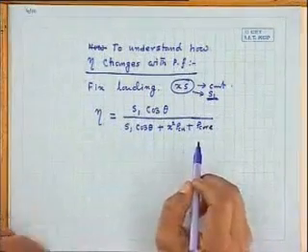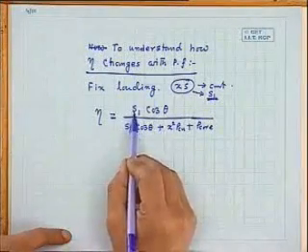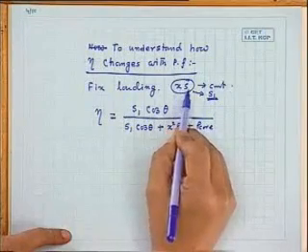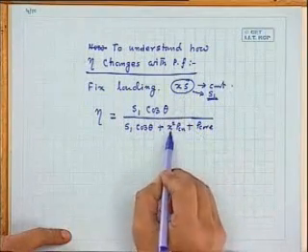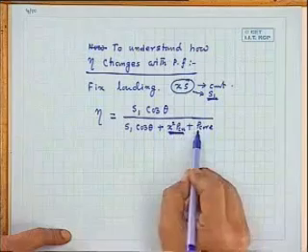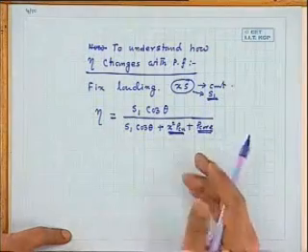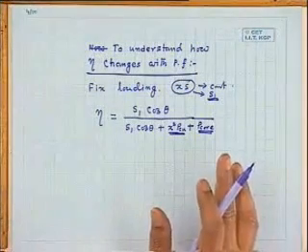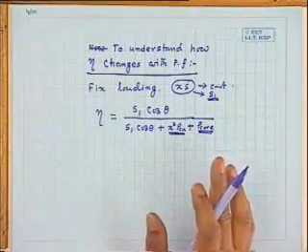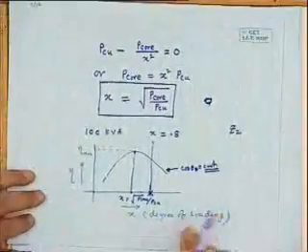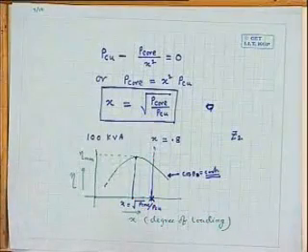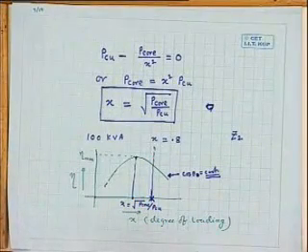Suppose I call this some fixed loading S1. But what I am trying to tell is, the moment you fix S1, the kVA loading, which is equal to x into S, both copper loss and core loss become fixed. Core loss is fixed, no doubt. You imagine that the transformer loading is varied in such a way that the kVA at which it is operating is constant, so that copper loss remains constant. You are only changing the power factor of the load.